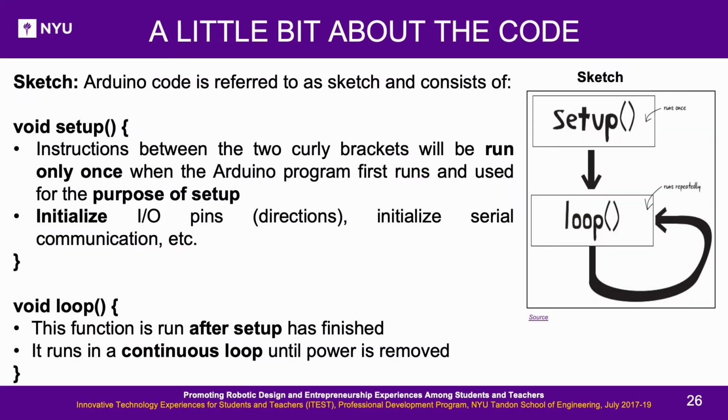A little bit about the code. Sketch. Arduino code is referred to as Sketch and consists of void setup. Instructions between the two curly brackets will be run only once when the Arduino program first runs and used for the purpose of setup. We have to initialize input-output pins, initialize serial communication, or sometimes also write a piece of code which needs to be run only once in here.